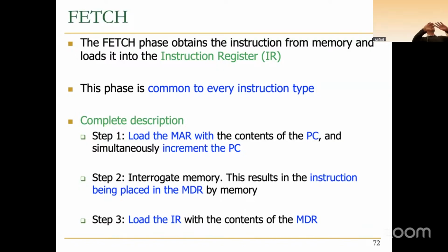We're interpreting the data at that location as an instruction, right? Okay, this is going to be hopefully clear later on because we're going to access memory in some other stage also. We're not going to put the data into the instruction register. Just because we're in the fetch stage of execution, the control unit is putting the data value coming out of memory into the instruction register. So we're treating that data value in memory as an instruction.